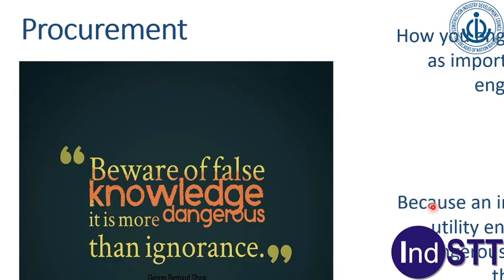So how you engage a SUE provider is as important as whether you engage one at all, because inaccurate subsurface utility engineering data is as dangerous and at times more than no data. So the SUE service provider should be responsible for accuracy and reliability of the data delivered. Accountability is the key. Written quality assurance procedures, it's an interpretive science, so experience is critical. Equipment inventory is very important because no single equipment can provide all the information. So you need to have GPR, you need to have acoustic locators, you need to have induction locators, etc. There should be internal CAD capabilities and, of course, timely performance.